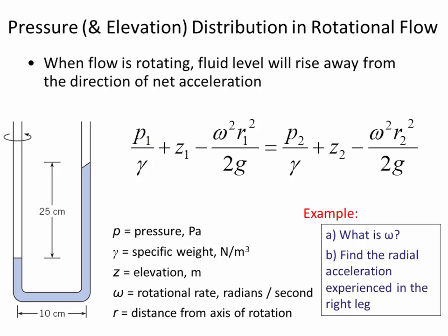So if we wanted to convert that into RPM, how many RPM is that? That's a classic quiz question, to throw in the RPM and radians per second combination so that you have to calculate one and then switch it to the other. So 22.15 radians per second, if I divide that by 2 pi radians per revolution, I've got 3.525 revolutions per second.